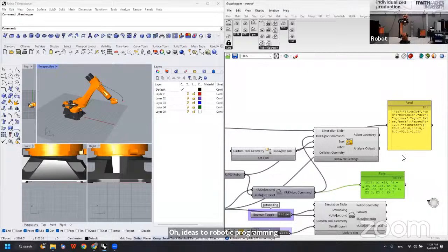For me, this is amazing because all of a sudden I could have a welder on one robot, and instead of connecting it to the IO of the robot, it's just getting an MQTT-based JSON string. So I could take that robot and put the welder on a different robot in 10 minutes, rather than calling up my electrical engineer and saying, I need a new CAN bus system built in hardware.